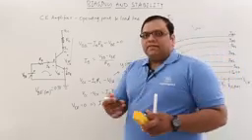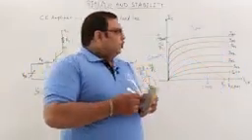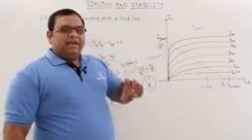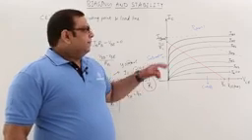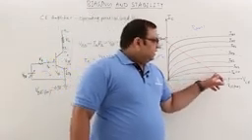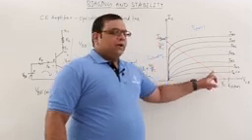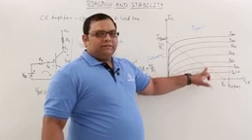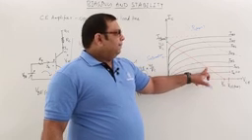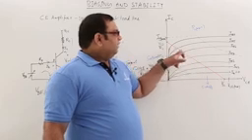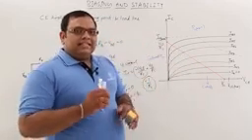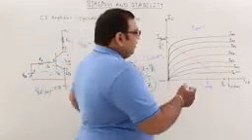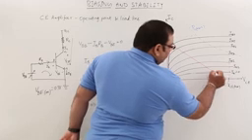Now what is the advantage of load line? From this load line we can understand where we can operate the transistor in this region. This load line is intersecting with the output characteristics, at this point with IB is equal to 0, and when you increase the IB, let us take IB1, it is intersecting here, IB2 here, IB3, IB4, IB5, IB6. So let us consider you are operating the transistor at IB1, at this point.